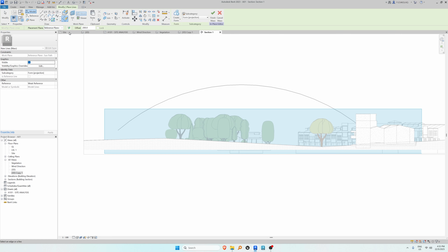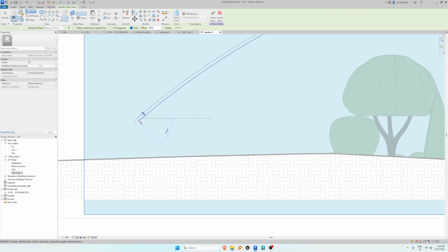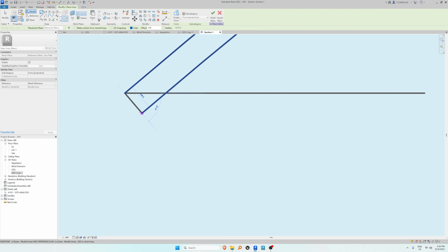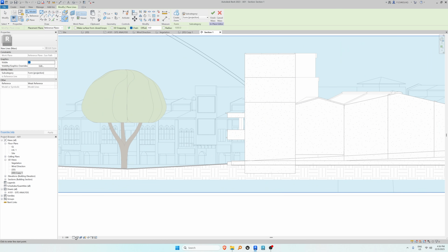Make sure it's set to this. It's set to draw on work plane. Like this one, pick line. Okay, this is correct. Now we just close it. Don't forget to remove this, the offset. So here, close the shape. Back here, if you cannot see it, change it to wireframe.